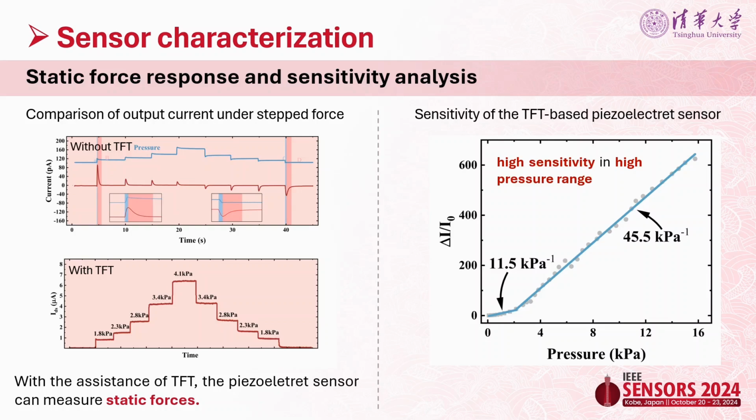The sensor with TFT can exhibit staircase waveforms with the pressure increasing from 1.8 kPa to 4.1 kPa, and can maintain unchanged under static force. Overall, with the assistance of TFT, the piezoelectric sensor can mirror static force.